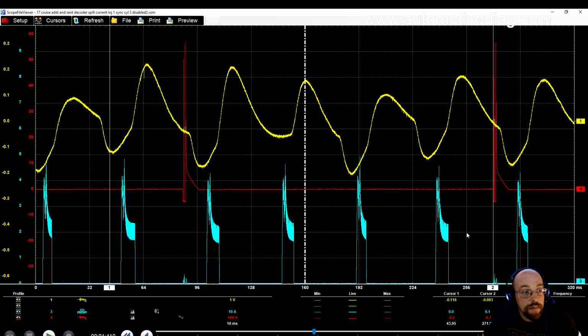And this frequency mode will allow us to do a misfire test based upon the mass airflow sensor or the crank sensor, very similar to what can be done with the math channels on a PicoScope. The difference is it will be able to be done on any scope, plug and play, with no math channels. But then you can actually see individual misfires as cylinders decelerate and accelerate. Pretty excited about that. It's going to be good.